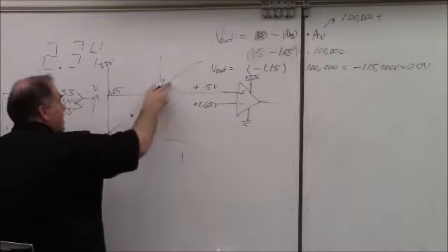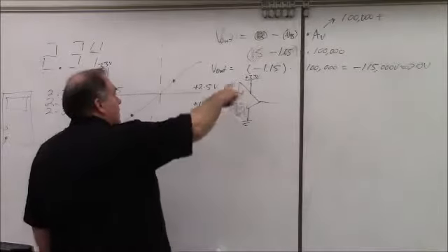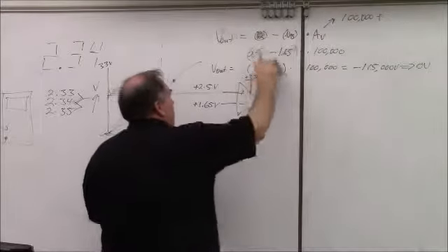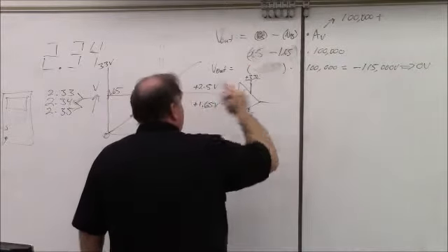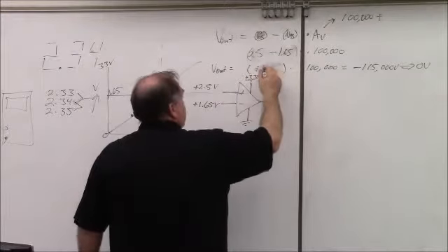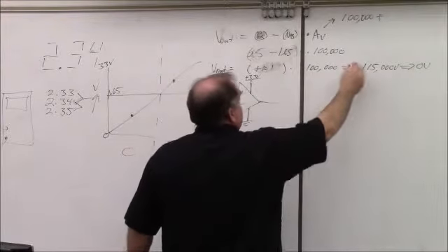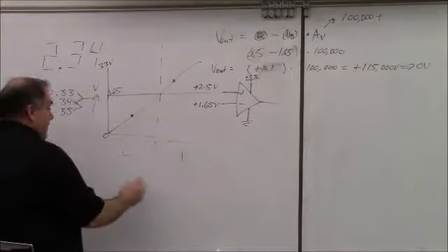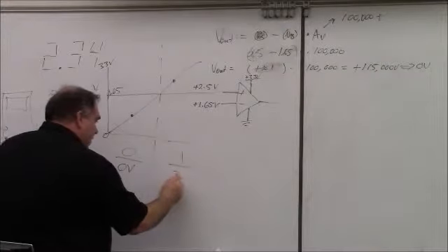But as the voltage goes up, and we're up here at 2.5 volts, now the sign changes, and this becomes a positive number. So this will be some positive number around approximately 1. So 1 times 100,000 is positive 100,000 something, but we can't get above 3.3 volts, so we get 3.3 volts out. So this would be logic 0 or 0 volts, or logic 1 and 3.3 volts.